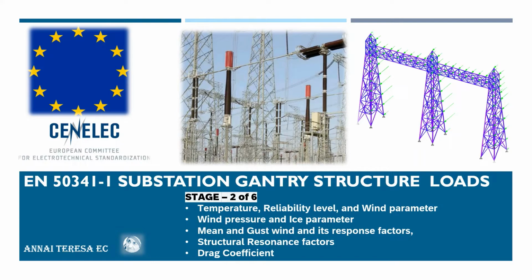In this video, we are going to discuss stage 2 out of 6 for substation gantry structure loads using European standard EN 50341 part 1. In this, we are going to discuss the temperature, reliability level, wind parameter, wind pressure and ice parameters, mean and gust wind load comparison and its response factors, structural resonance factors, drag coefficient.